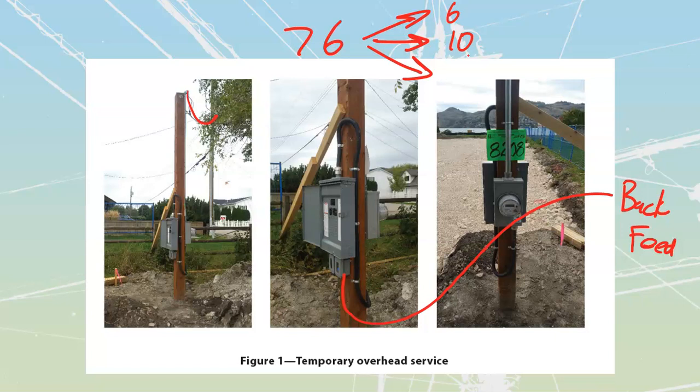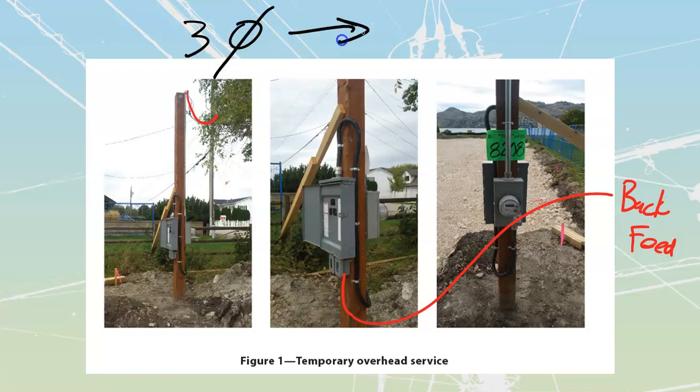If you go to section 24 as well, you'll find out that there is, bonus, a second three-phase colors set inside of that section 24. Section 24 is to do with isolated systems inside of a hospital. It's a particular type of system that you have to have isolated from regulars, so that if there's people on heart machines and stuff like that, that's not going to screw them over if there's any transients on it. So they create these specialized isolated systems, and they have this other system that is composed of three different colors. I'm not going to tell you which one it is, because then you never look this stuff up yourself, but I'll test you on it later on to find out if you did.